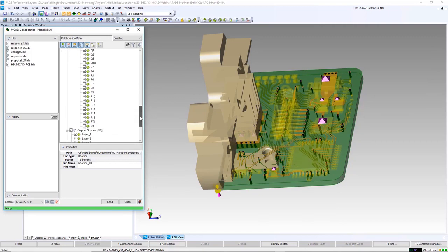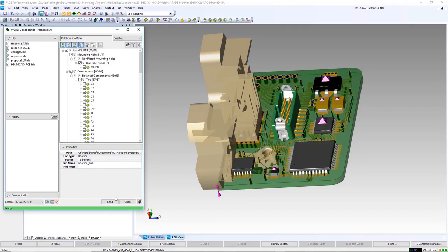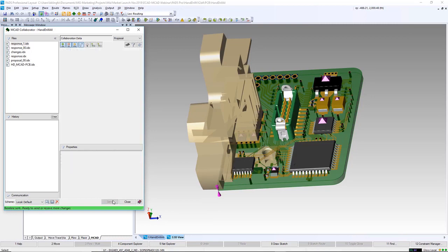The important one, if you want metal to go over, is to choose all the electrical layers. Once you hit OK, you hit refresh, and in the list down below, you can see all of the objects that will pass over to MCAD. Using the checkboxes, you can deselect the items that you choose not to pass.